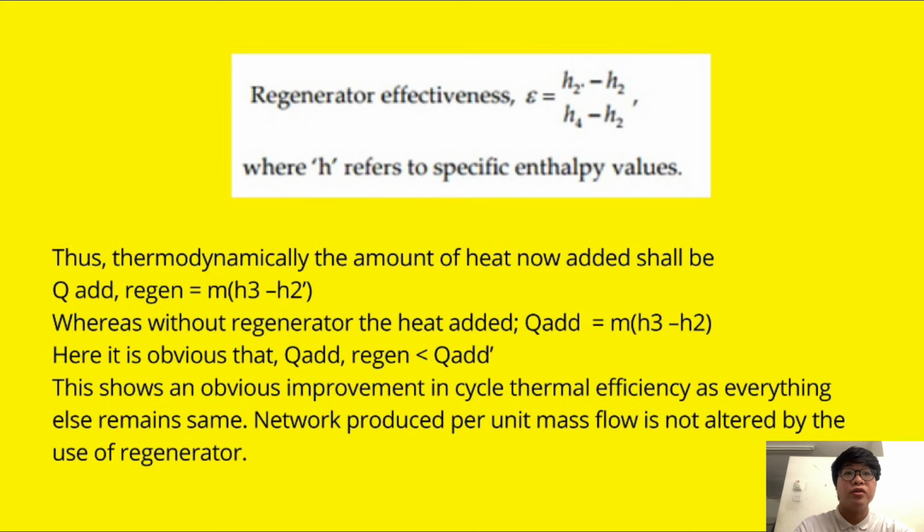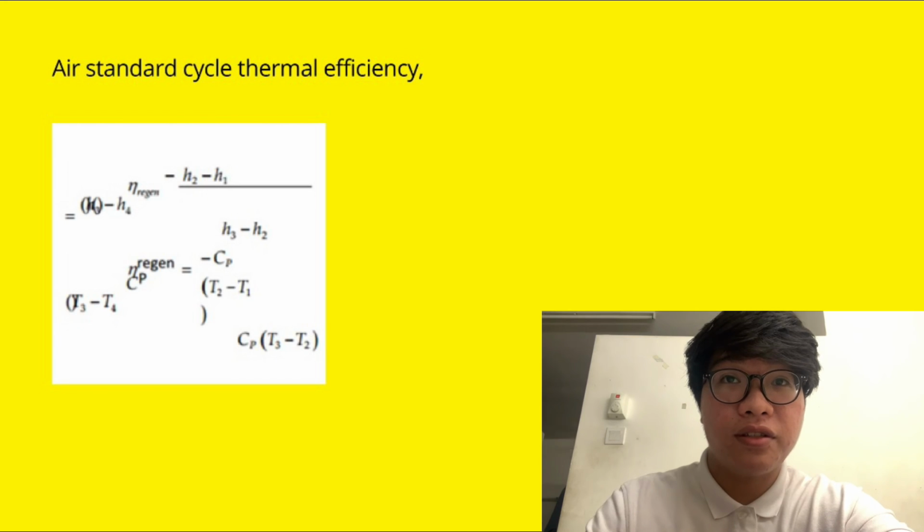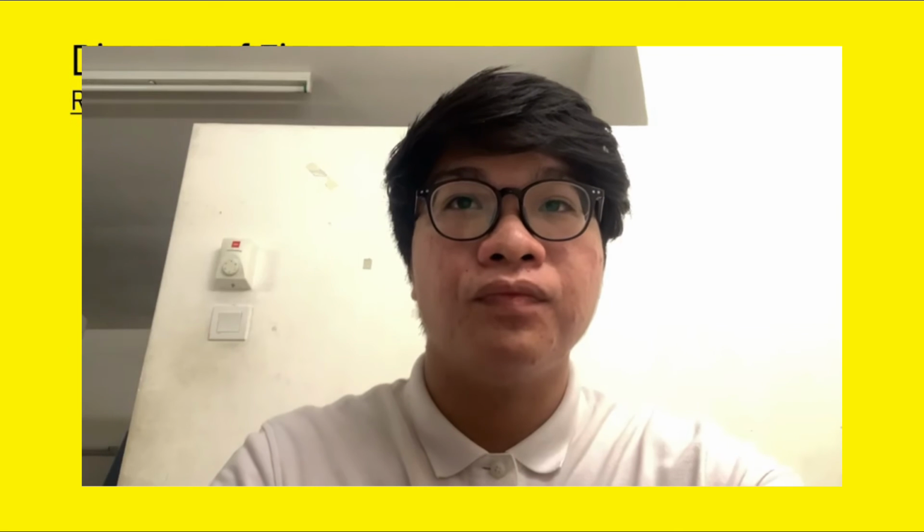The work produced per unit mass flow is not altered by the use of a regenerator. Here is the standard cycle thermal efficiency. This is the diagram of the regeneration gas turbine cycle.